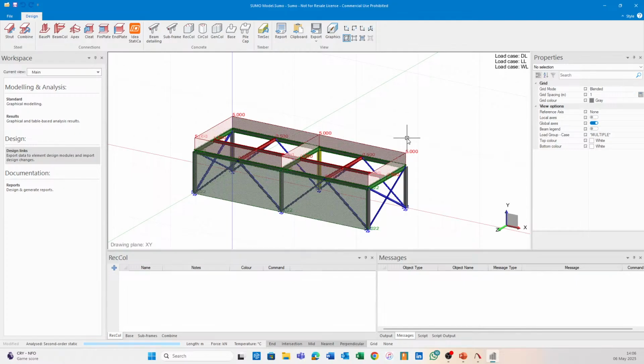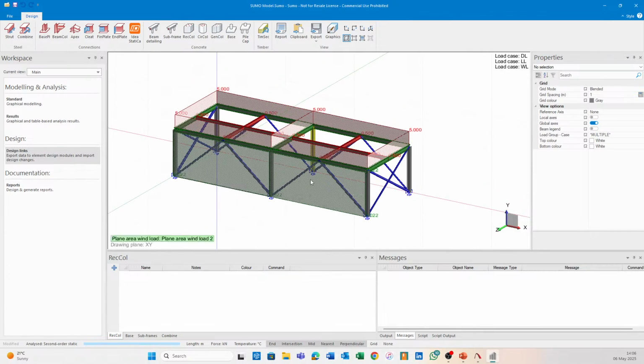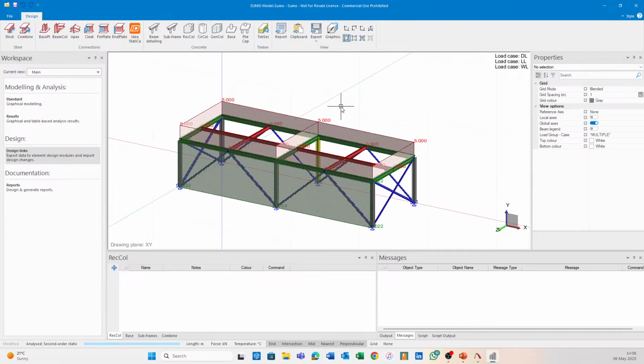All right, so your analysis is analysis, right? So a bending moment in China is a bending moment in South America, is a bending moment in Greenland, is a bending moment in South Africa. But design is done in accordance with a specific set of national codes, or in some cases, as we'll see now, we'll do that according to the Eurocode, which can be tailor-fit to a specific country using national annexes.